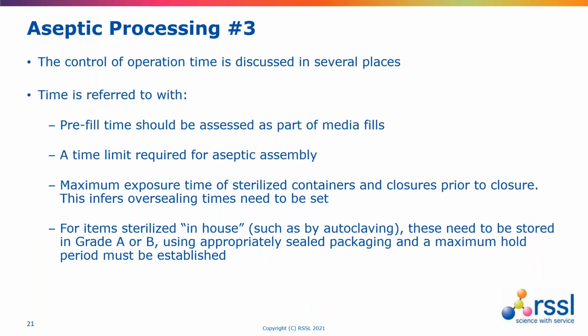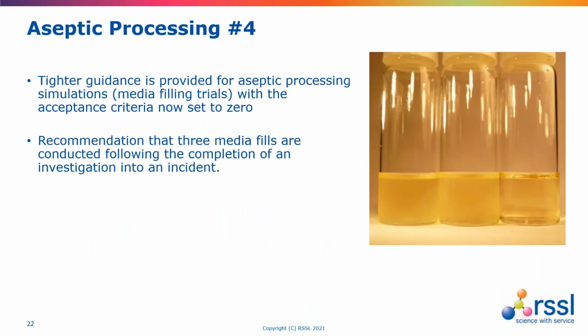And it also stands with media fills or aseptic process simulations, that here more time-based criteria is evident as well. So we've already had things like assessing the filling machine hold times and sterilized equipment hold times, but we also have a very strong indication that the media fill runtime should be equal to or slightly greater than the typical product fill run times as well, and something that becomes slightly more complicated when we're using isolators for campaign filling as well.